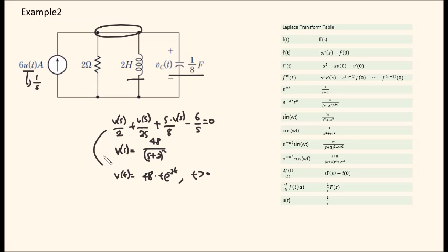Here we have seen how much simpler everything has become. So I strongly suggest you use the Laplace transform when solving RLC circuits. And I strongly suggest that you memorize some of the important Laplace transform table, because once you get used to it, it's not that hard to memorize and it will help you in so many ways.